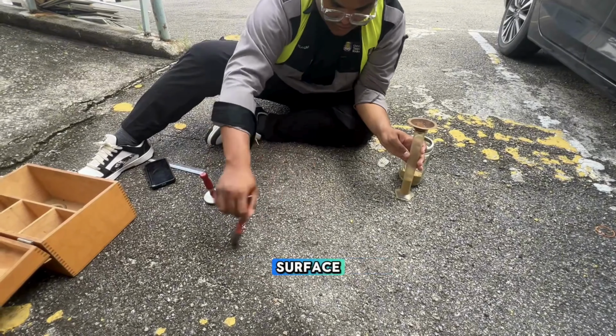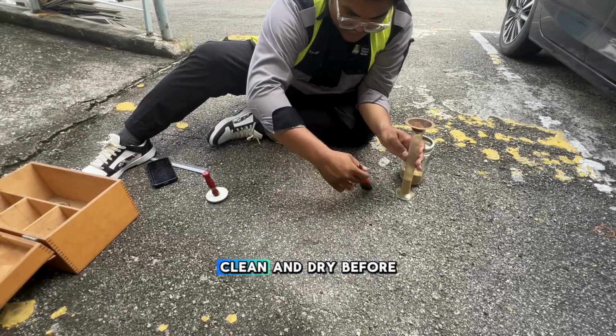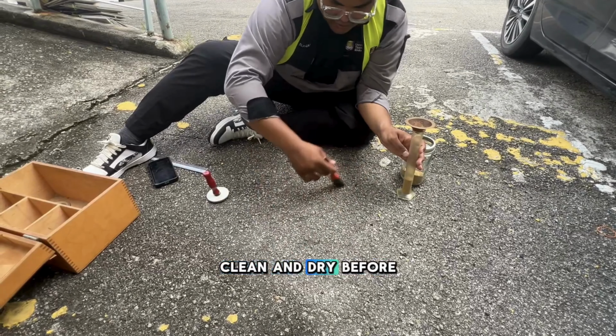First, for the rough surface, the test surface is cleaned and dried before the testing. Second, 50 ml of sand is poured onto the pavement surface. After that, the sand is spread evenly in a circular motion until the surface voids are filled. Next, the diameter of the sand patch is measured using a ruler. And don't forget to record all the data.